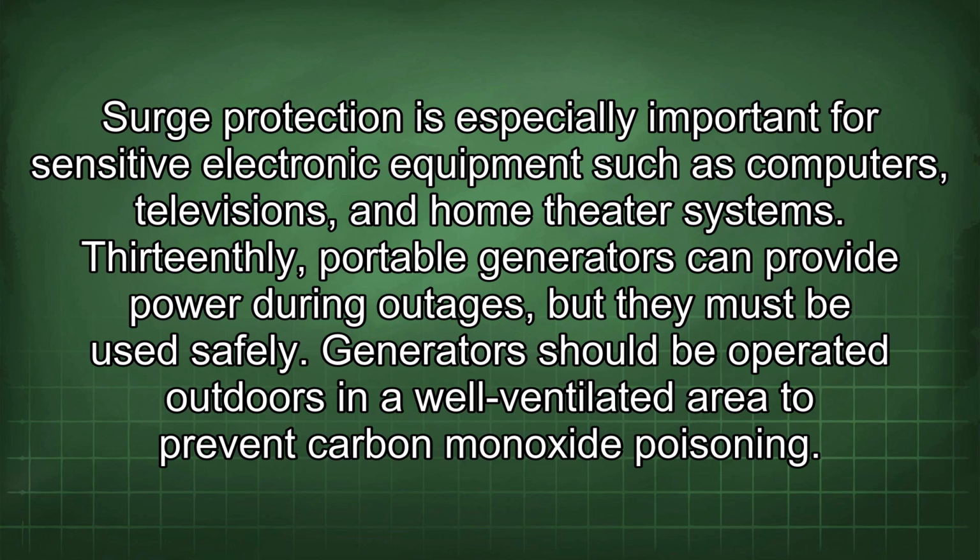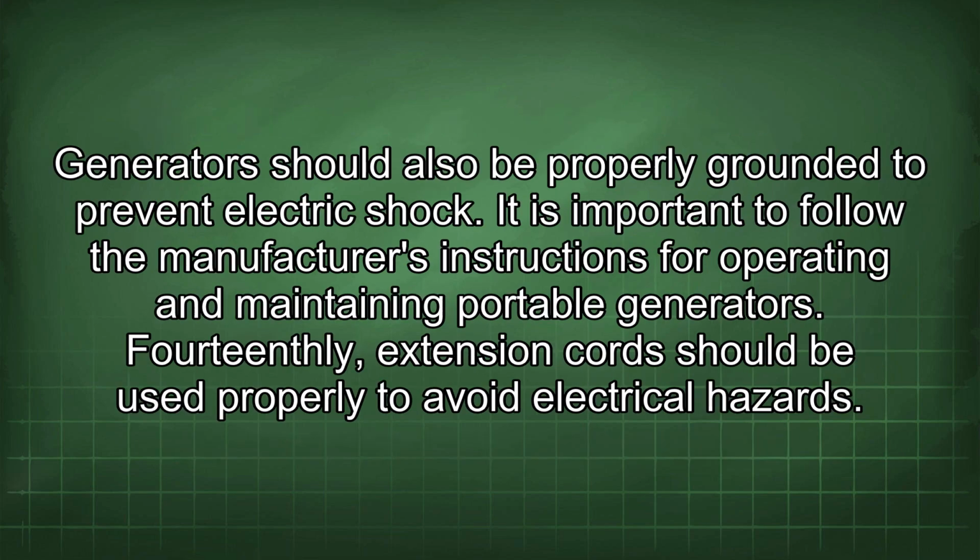Thirteenth, portable generators can provide power during outages, but they must be used safely. Generators should be operated outdoors in a well-ventilated area to prevent carbon monoxide poisoning. Generators should also be properly grounded to prevent electric shock. It is important to follow the manufacturer's instructions for operating and maintaining portable generators.